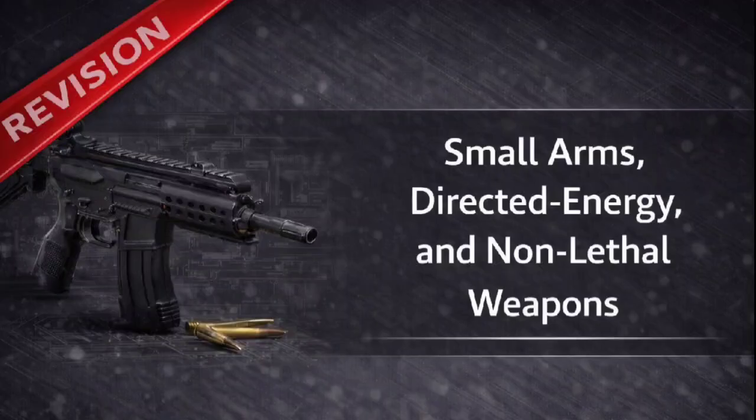Why does muzzle jump fundamentally prove that perfectly accurate automatic fire from a handheld shoulder weapon is a mechanical impossibility? Muzzle jump defines the absolute limitation of automatic infantry fire. The sequence is fixed. The first bullet in a burst hits where the operator aimed. As it should. But the immediate rapid recoil and vibration cause the muzzle to rise, and to rise rapidly. Because the automatic system fires so quickly, the second and all subsequent shots in that burst will inevitably leave the barrel on a trajectory pointed higher than the correct line of sight. And a human can't counteract that force quickly enough. No human can. Therefore, the weapon simply cannot produce perfectly aimed automatic fire.